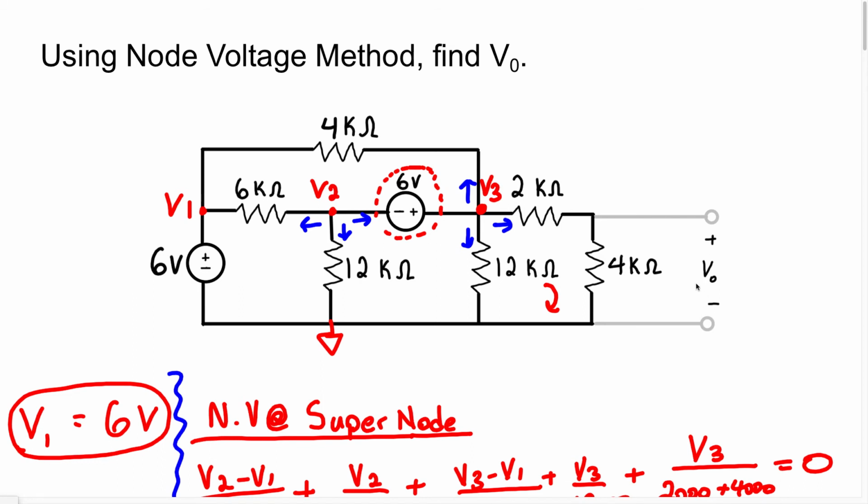And another way we can solve this problem is because we have two resistors in series, and we know the total voltage that's going to be passing through these resistors. To find the voltage across one of these resistors, we can actually just use voltage division. So voltage division is probably going to be our easiest way to solve this particular problem. So that's what I'm going to do, right?